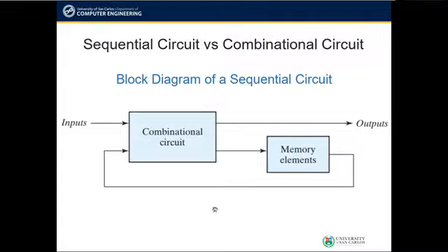So unlike a combinational circuit, in a sequential circuit, knowing simply the inputs does not guarantee that you will be able to know the corresponding outputs, since there are internal inputs, outputs, and state that you need to consider. In this unit, we will explore how these memory elements function in sequential circuits and how they are designed and implemented.